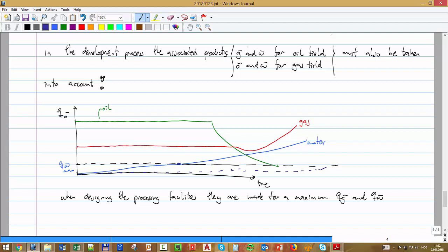What happens here? Do you think I will be able to keep producing that profile? No. What are the solutions here? Shutting the wells. That's one thing. Water injection. Another will be to ask for some more money and try to make a change in my platform. But the simplest is to choke down production, and use, for example, a lower rate, just because I'm producing too much water.